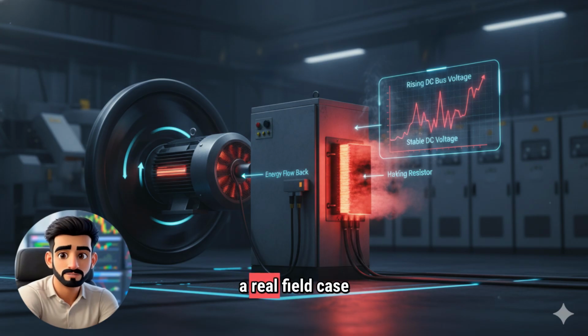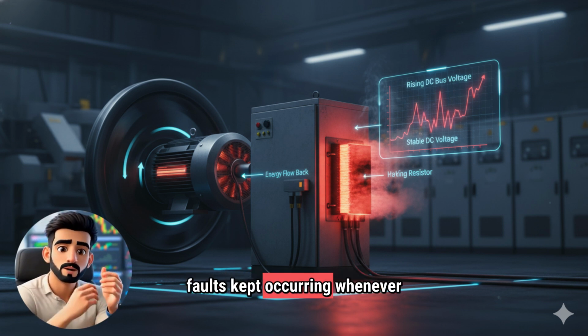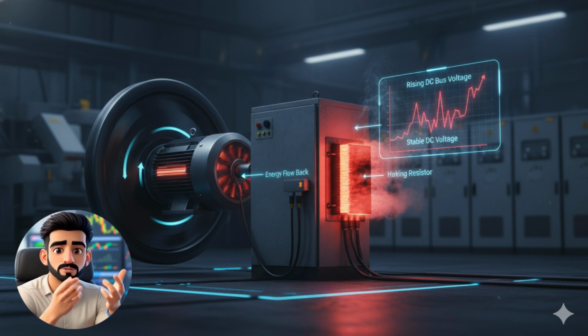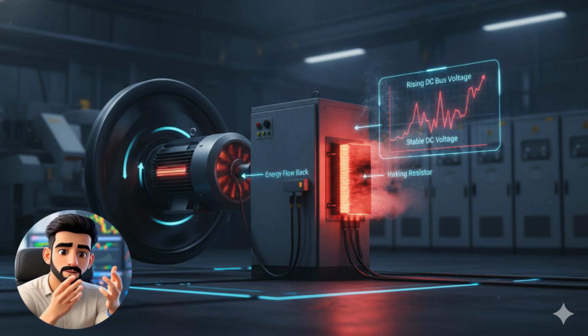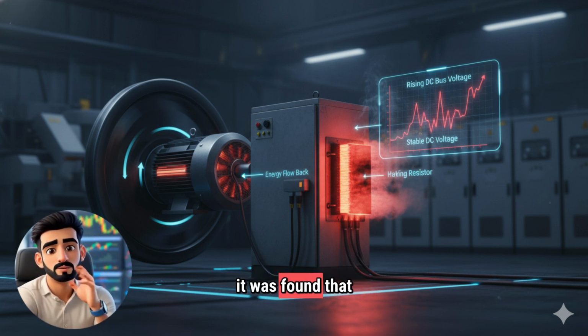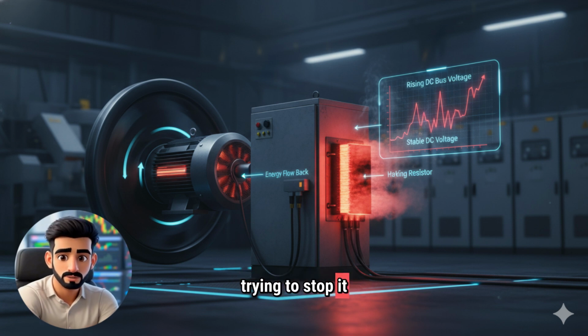Let's now look at a real field case study. In a plant, overvoltage faults kept occurring whenever the operator gave a stop command to the drive. The maintenance team first installed a braking resistor, but the fault still occurred occasionally. When analyzed in detail, it was found that the deceleration time was set very low. The motor was driving a heavy inertial load, and the drive was trying to stop it quickly.